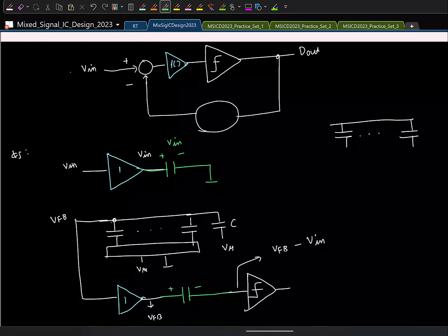But now let us see what happens when we have nonlinearity, right? So this is now nonlinear. Are there two different buffers? Same buffer, right? That's the whole point. Single buffer used at two places. See, the point is we are not doing these two at the same time. We are going to sample once and use the same buffer for buffering this. Once. When you are feeding V in is here, right? That's where we have sampled the input.